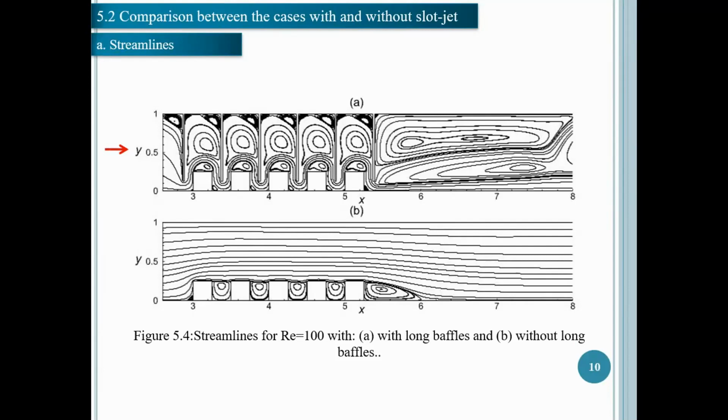The long length of the baffle makes the flow penetrate the gaps between blocks, which breaks the stagnation of the warm air stacked in this region, as detected for the case without baffles, figure B. A moderate size vortex is shown above each block, horizontal face.